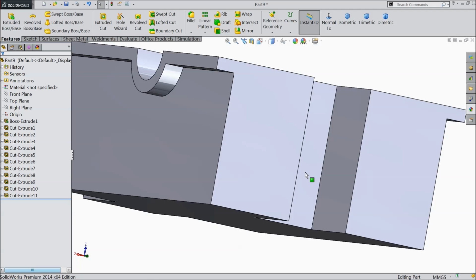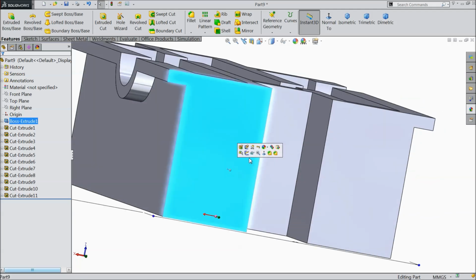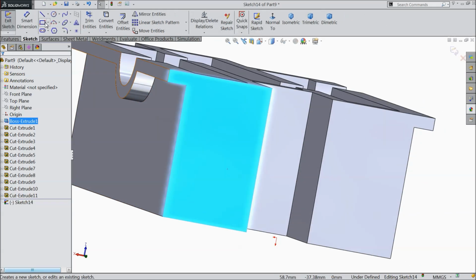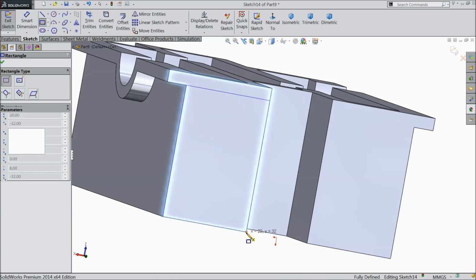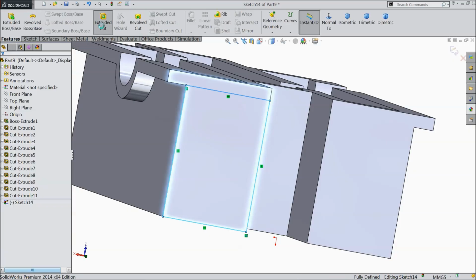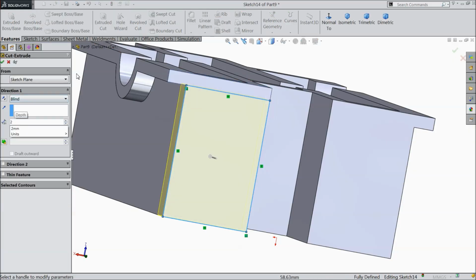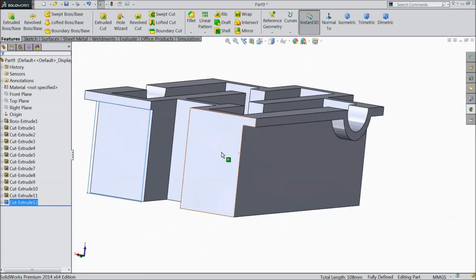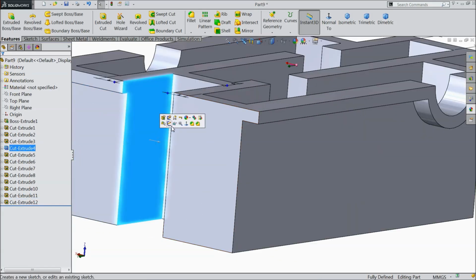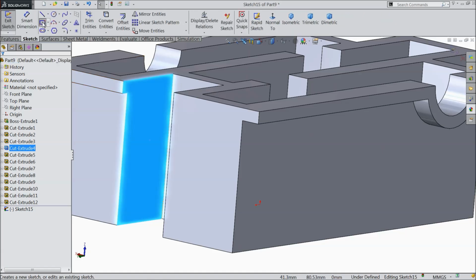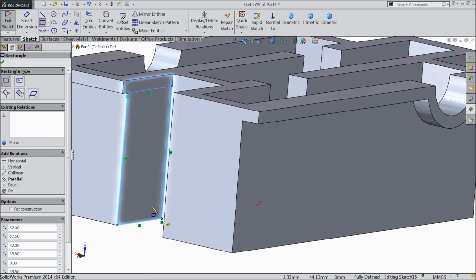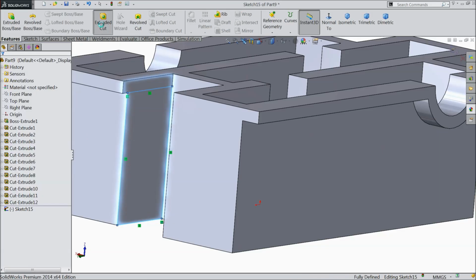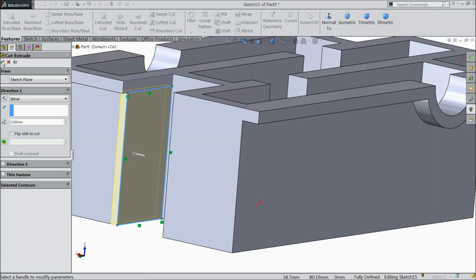Now the opposite direction balance, select this face, sketch, corner rectangle, this corner to this corner, extrude cut, keep 2 mm. Okay. Now the same as here inside sketch, select this corner to end, extruded cut, depth 2 mm, okay.